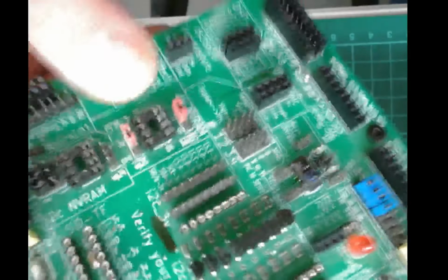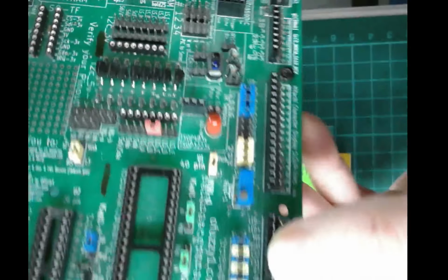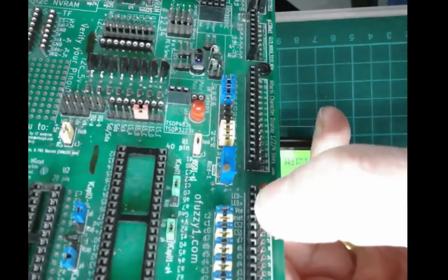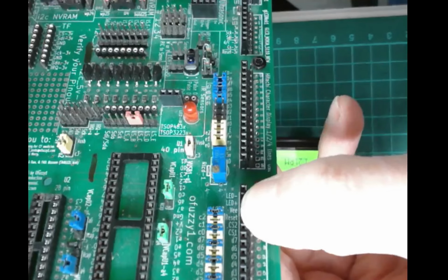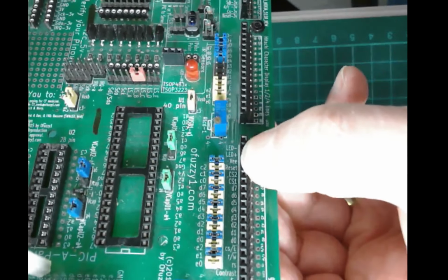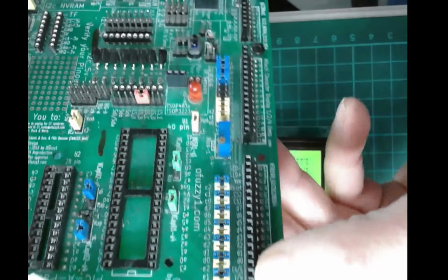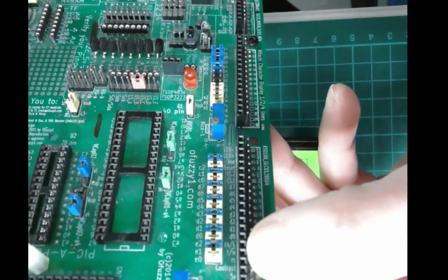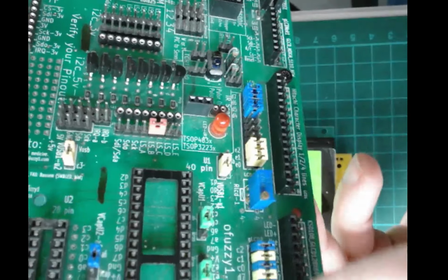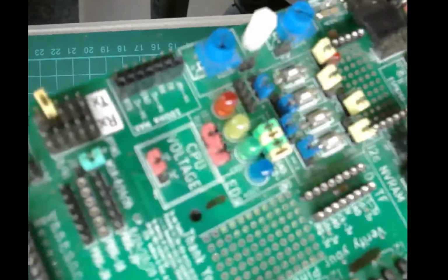what we've got here is a load of connections on this board. It says here LED plus VEE. It's just down here, like you can see it here. It's down where my fingernail is. Reset CS2 D7 through to, if you look right the way through, RS. And this connector here also has connections for 5 volts, ground, and the contrast. There we go. So this board was designed for this particular GLCD, and it worked well. So that's another board. For those who are counting, you've seen quite a few of these today. Okay.